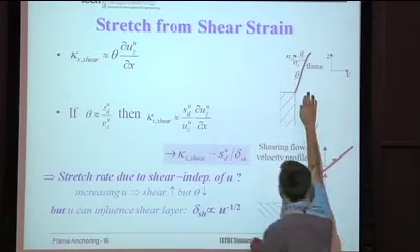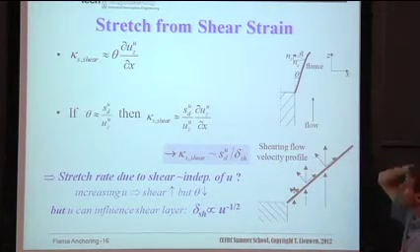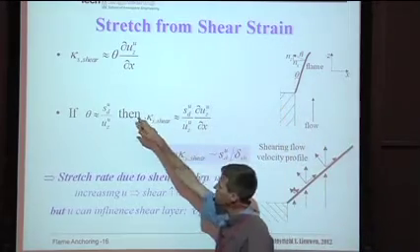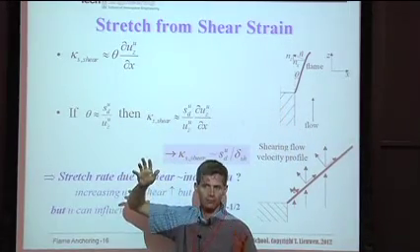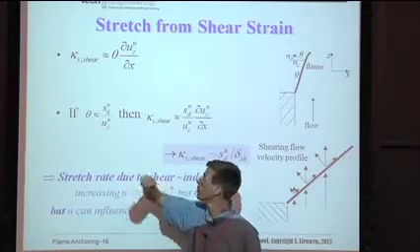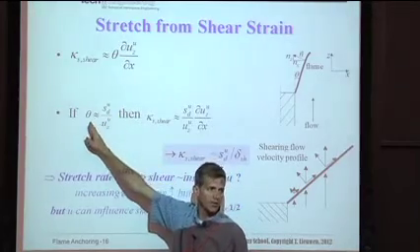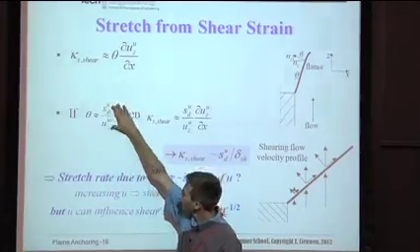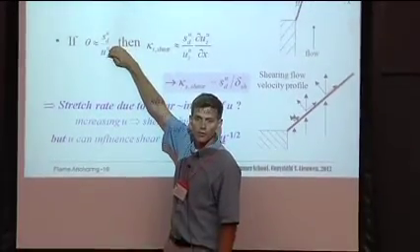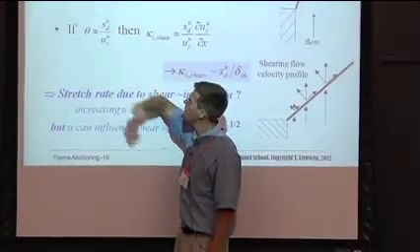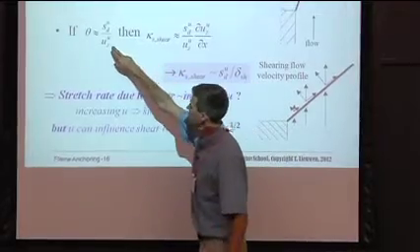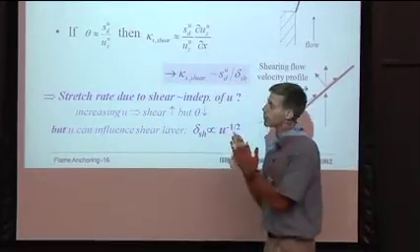If the flow velocity is high relative to the flame speed, which it usually is, a good approximation is that I can replace sine theta by theta. All right? So sine theta is equal to flame speed over u. Well, it's basically theta. And so theta will approximately equal the flame speed over the flow velocity. And so as the flow velocity becomes very large relative to the flame speed, theta approaches 0.